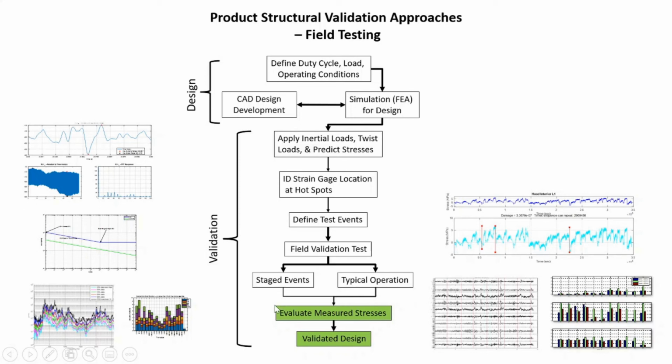We can also look at the data from a statistical standpoint and be particularly interested in perhaps some rare large events. Sometimes these can be very significant. The fatigue damage of a continuing number of large events can add up fairly quickly, even though the number of events isn't huge. So much of the data that we'll be examining, we'll be looking at from a fatigue standpoint.